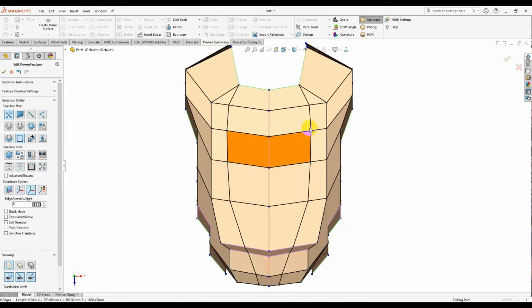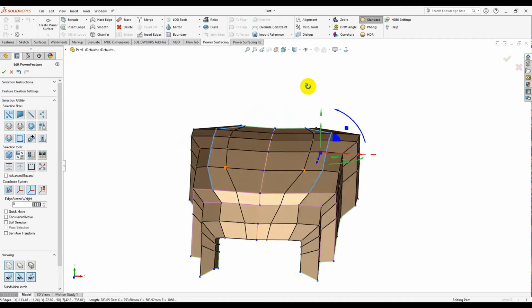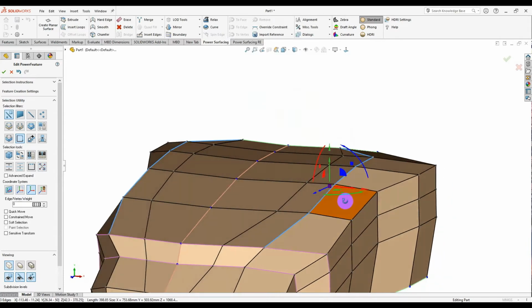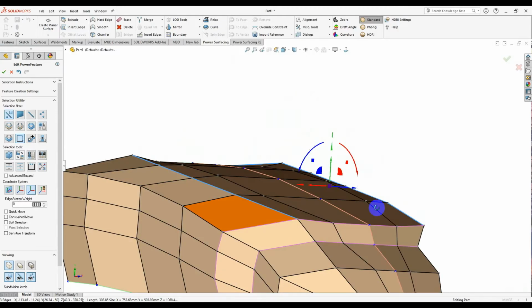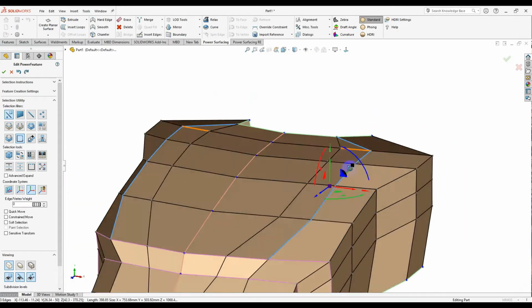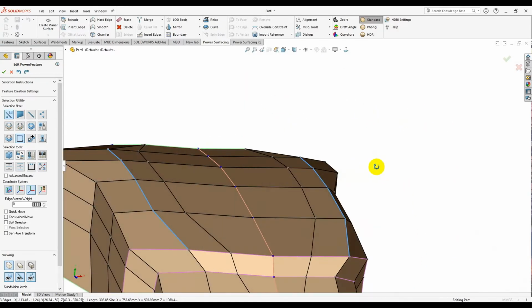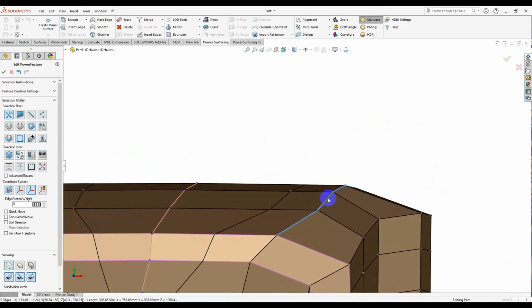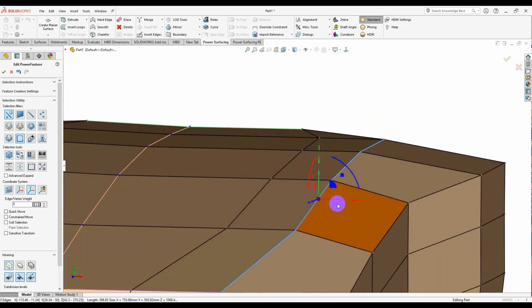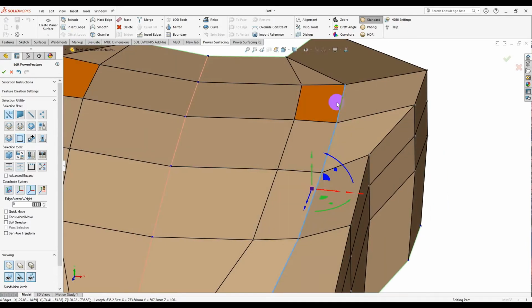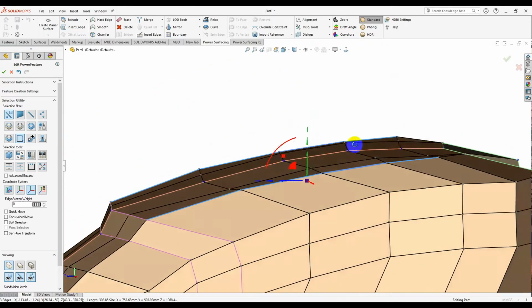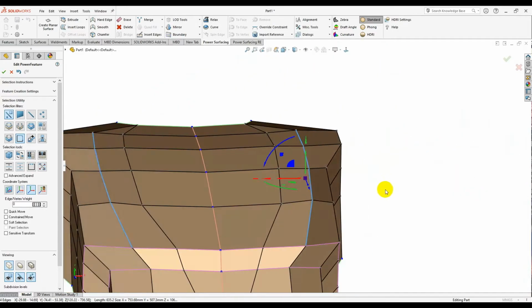Now get the top view. I'm going to select this whole set of lines, right click and use the flatten, so it's going to flatten it like that. Let's unselect this one here, so it's just going to flatten these 4 lines. So now it seems to be nice.